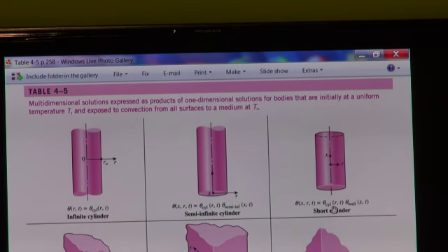Many people make a mistake in not choosing the correct dimensions. Okay, so in terms of the plane wall, we need to get the temperature at the center. Now previously, when we looked at the plane wall and we said we want the temperature at the center, we were sort of thinking of the temperature there. But remember, it is a one-dimensional problem. This thing is very, very long, and boundary conditions are on that side and on that side. So this is actually the temperature on a line everywhere. Okay, it's not the temperature only at one point.